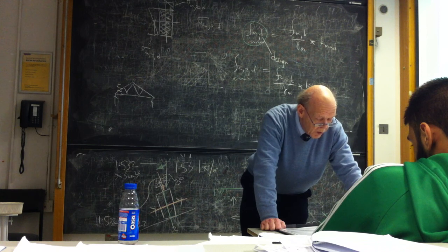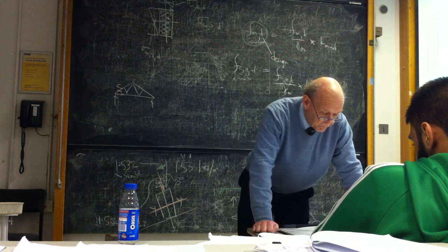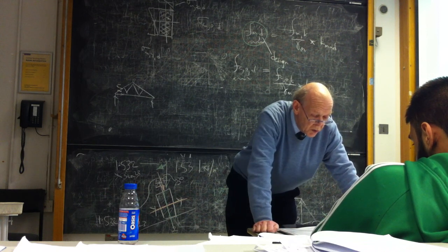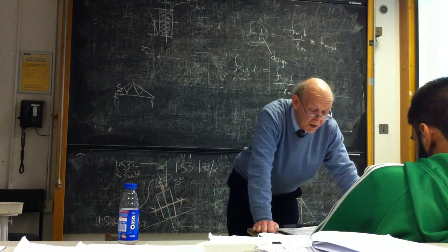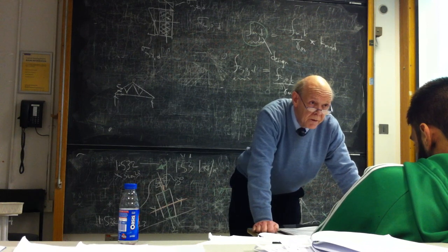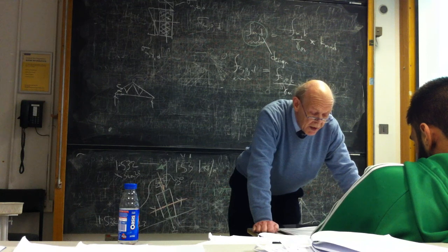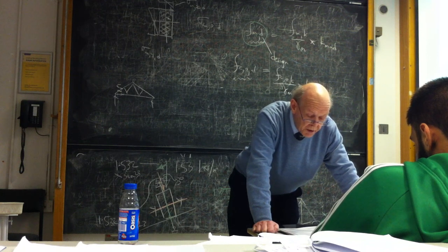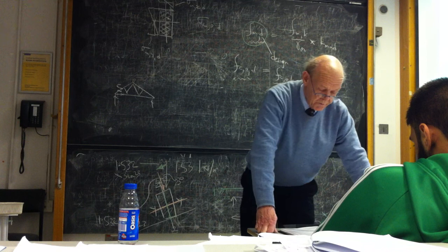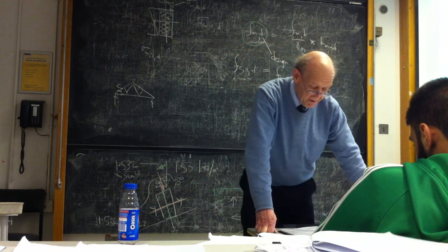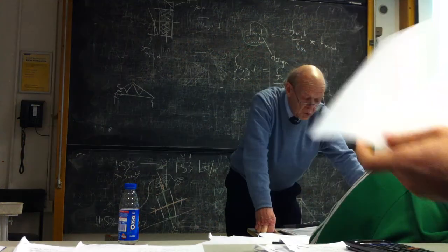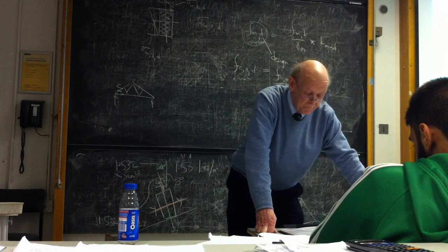So you have to work out ky and kz. Having got those, you can work out two coefficients called kcy and kcz. And then you can stick them in the design formulae, so 6.23 and 6.24, which would be quoted for you in an exam paper.